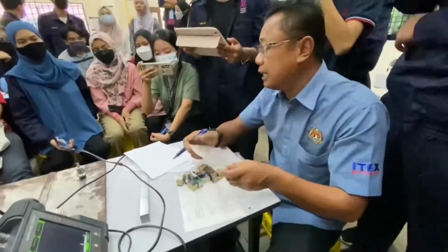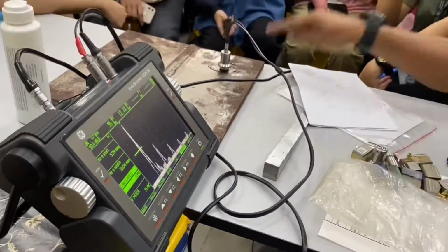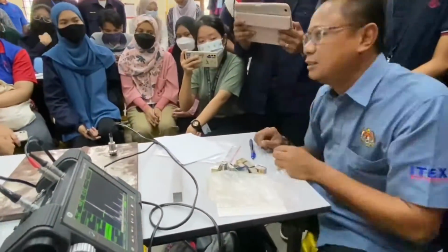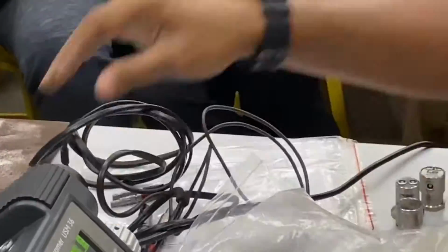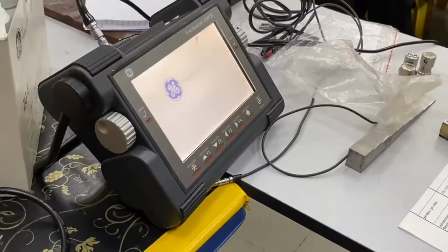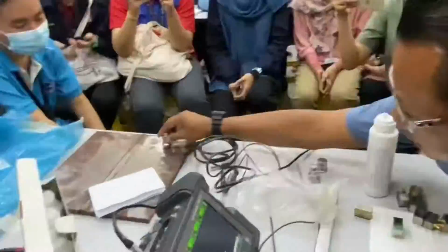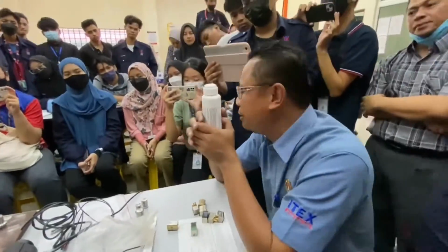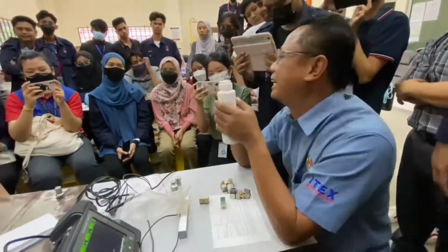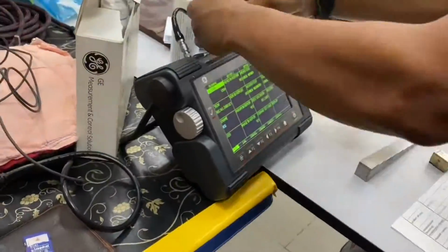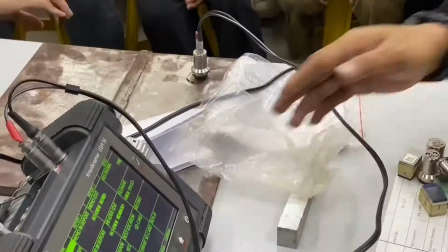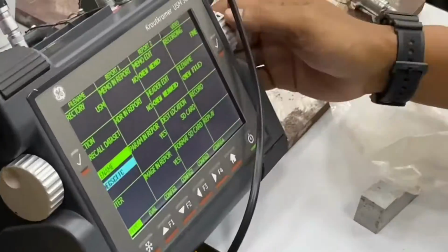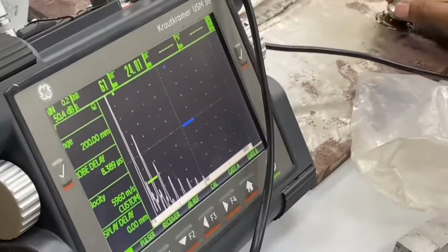When driven by the pulses, the transducer generates high frequency ultrasonic sound energy into the material in the form of sound wave. When there are discontinuities such as inclusion, porosity, crack, and so on in the sound path, part of the mechanical energy will be reflected from the discontinuities surface. The reflected sound wave signal retrieved by the transducer is then transformed back into an electrical signal, and its intensity is shown on the display unit.